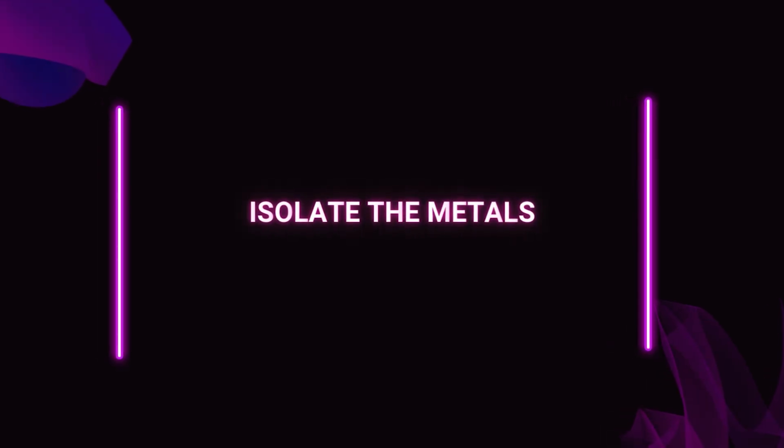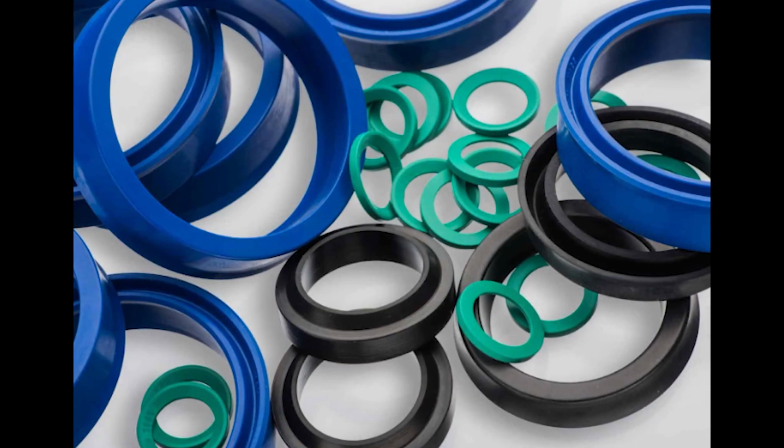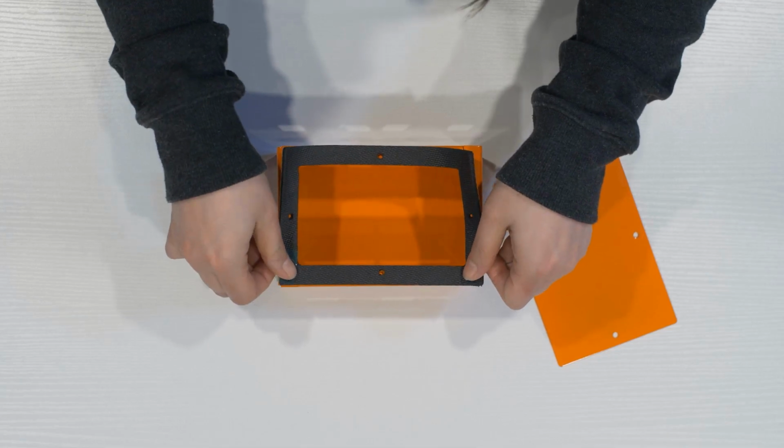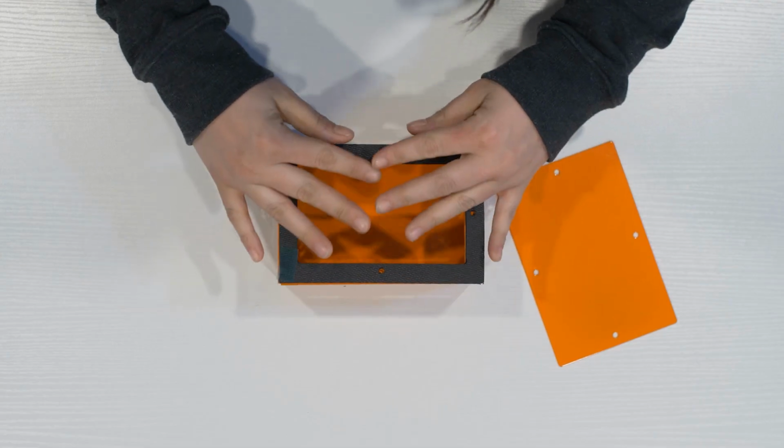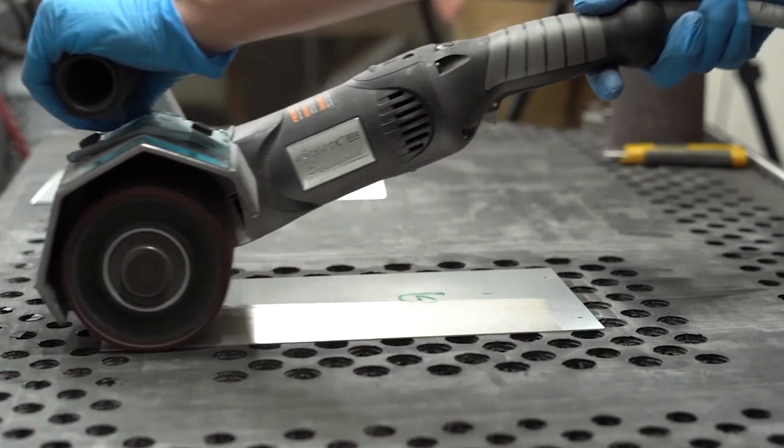Now, a risky pairing, for example, fastening a cold rolled steel part to a stainless steel part, can be problematic for corrosion. 2. Isolate the metals. If you must use metals that are far apart on the galvanic series, prevent them from making direct electrical contact. Use plastic or rubber washers under fastener heads, incorporate non-conductive gaskets between mating surfaces, and design for powder-coated surfaces to meet rather than bare metal.